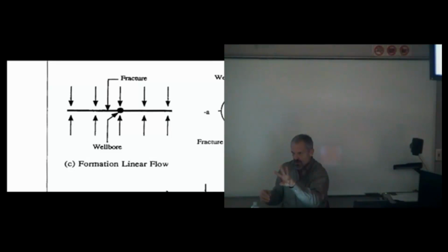And there's three basic unknowns: distance, time, and perm. I know how far apart I space my fracs. I can see on a decline curve analysis the time it takes for those fracs to interfere with each other. I get perm. I get a far better perm than I get in a Horner plot radial analysis.